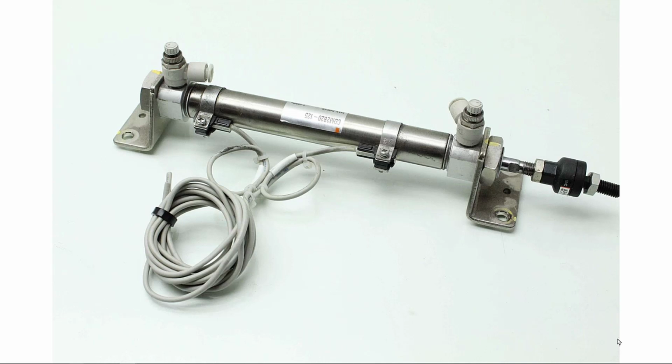Now there's a couple other features on this cylinder worth mentioning, and that is the ports. Notice there's an elbow on each port, and each of those devices has a fluted turn wheel and then a nut to lock it down. So this is how you adjust the airflow. So these are flow controls. Now this is one that's more or less like what you're seeing. It's a 90-degree elbow. Notice on the side of it, you have two symbols in parallel with the thread on the bottom of the symbol. What looks like a capacitor with an arrow through it, that's the adjustment. That's the flow control. The other thing is a check valve.